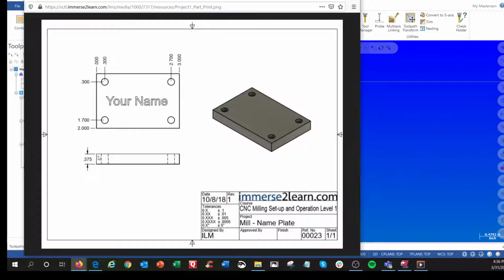So let's go with half-inch material because that's pretty much a standard size. And 3 inches long we can control by cutting it on a bandsaw, and 2-inch wide may not work. If you buy 2-inch bar stock, it may not be able to machine on both sides, especially if you're trying to hold this tolerance, which right here is 3 place dimensions. So let's use, I think we can get 2 1/4, which would be 2.25. So that'll be our plan on stock.